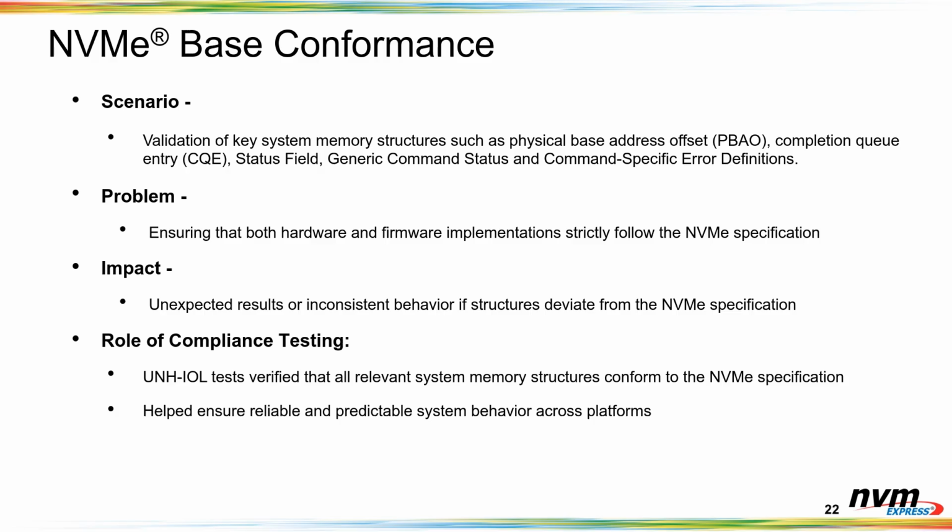Continuing for the base conformance, the validation of key system memory structures, such as physical base address offset, completion queue entry, status field, generic command status. So the problem is the same: we want to ensure the hardware and the firmware strictly follow the NVMe spec. If there is any deviation from these structures, there is a possibility of unexpected results or inconsistent behavior.